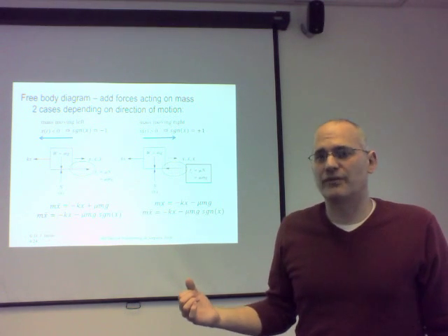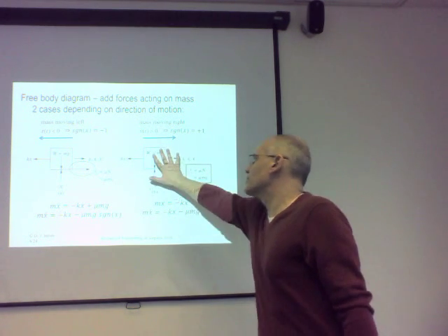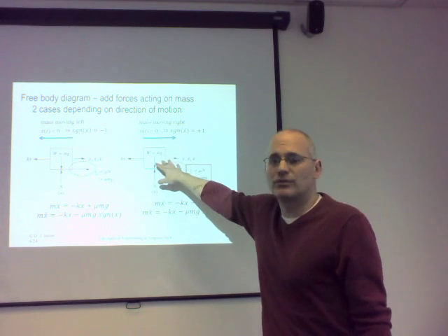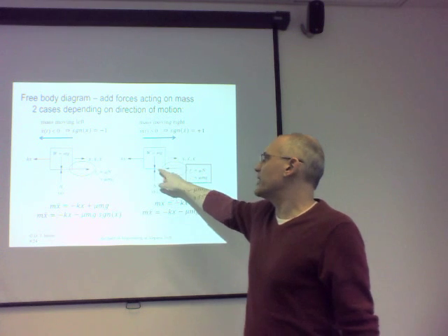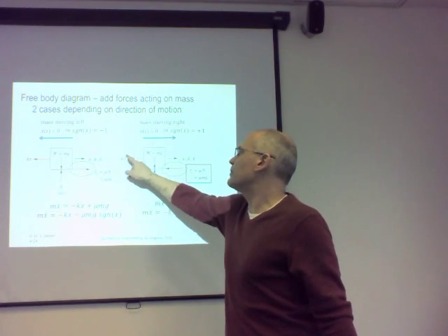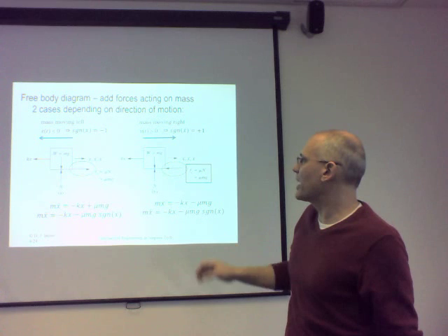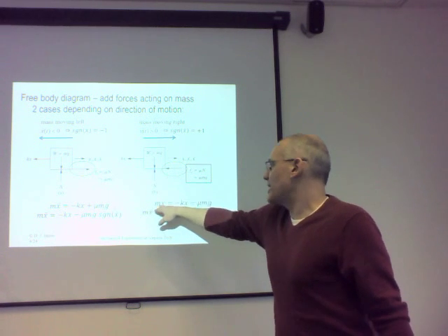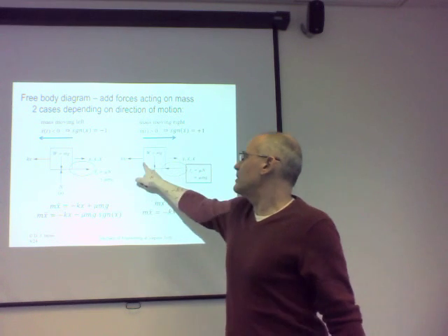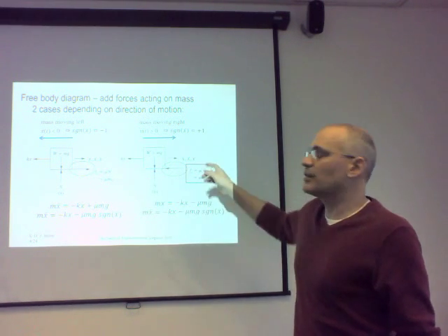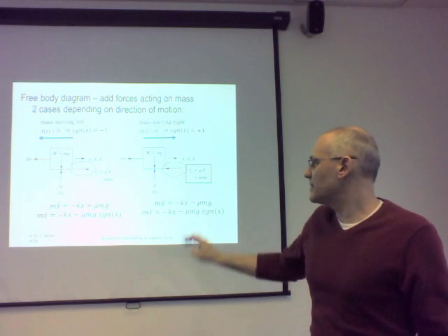Derive our equation of motion from our free body diagram. Here's our free body diagram. All the arrows and the definitions of forces are written correctly. We've got the arrow for the spring pointing to the left with a positive kx. That's correct. M x double dot is equal to minus kx to the left, and x double dot is positive to the right. So that's correct.